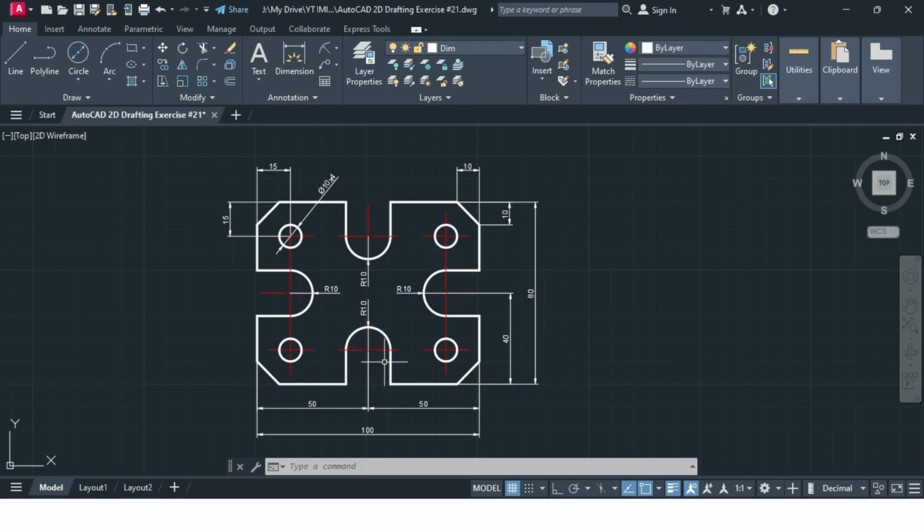We'll trim off the extra blank spaces. Then we will chamfer the edges 10 units on one line and 10 units on the other line, and we'll select every line so all four get chamfered. Then we'll trim off the unwanted spaces, put the center marks, and then do the dimensioning and we are done. So let me show you how we'll proceed with this drawing.